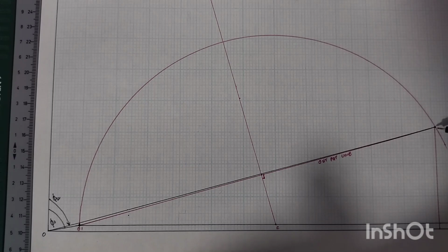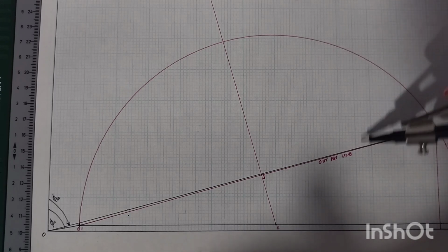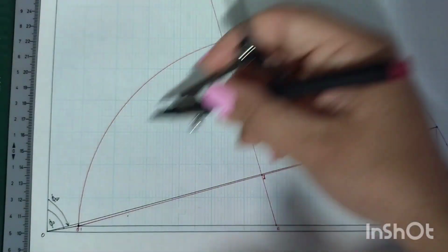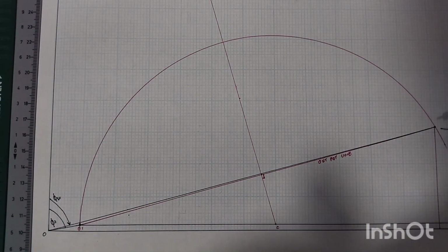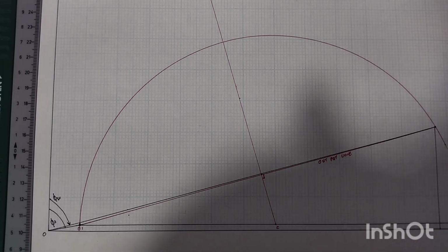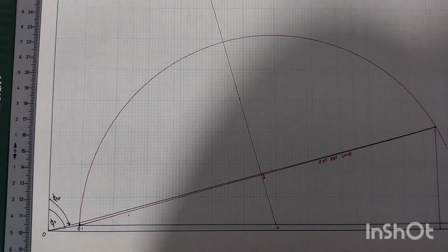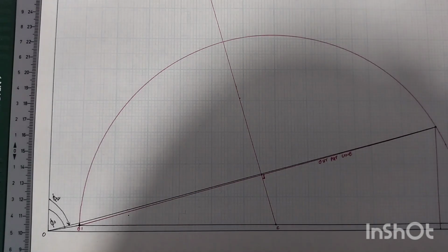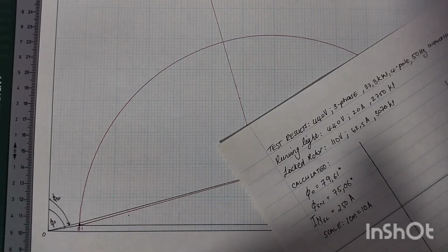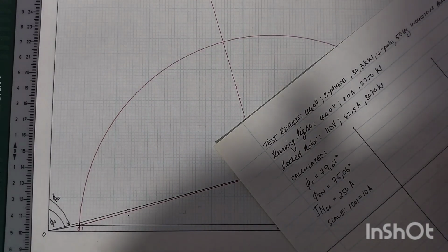You will notice that there, like I said, anything above your output line is your output at various loads. And as you already know, at standstill, at starting, there's no actual speed, and therefore there is no power out at that point. So for this example, I used equal rotor and stator copper losses. So for equal rotor and stator copper losses at standstill, you'll measure that line and you'll divide it by 2.